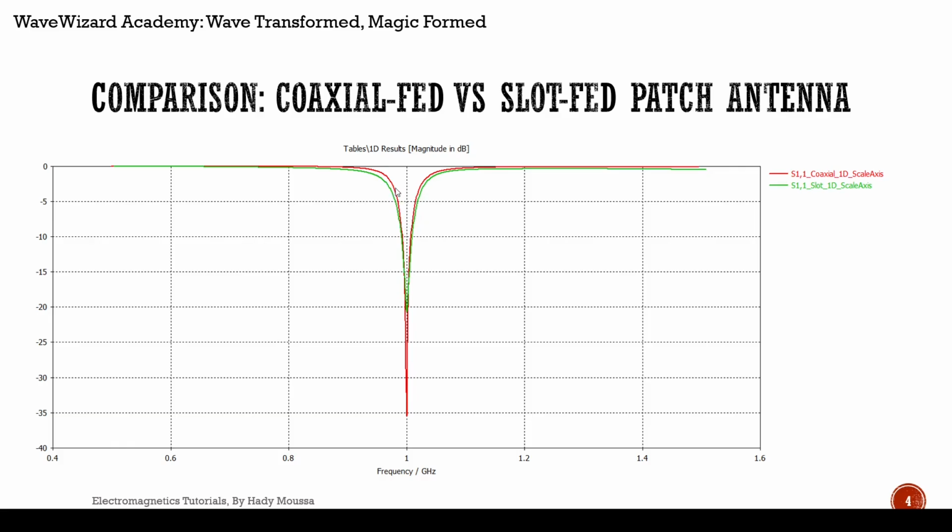It is clear that because the antenna itself is the same size, most probably the bandwidths are the same. There is a theory called the Bode-Fano limit, which means that for a specific antenna or resonator, if you want to match it, you are limited by the gain-bandwidth product. Here, for example, if you look at the 10 dB bandwidth, it's almost the same. The slight difference is because the peak here is lower.